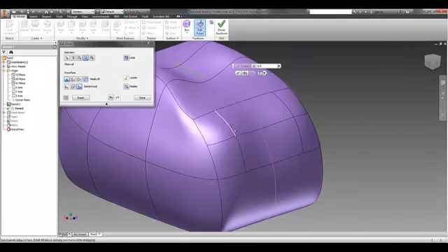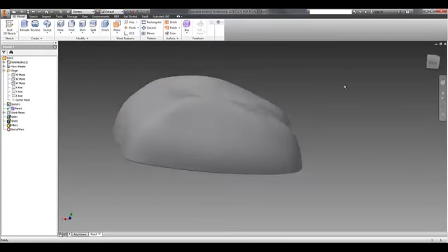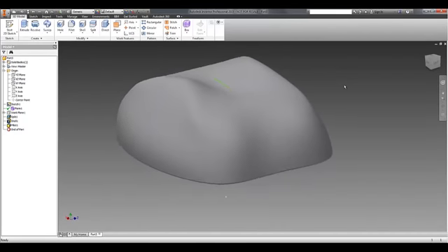Previously, without subdividing the face, I wouldn't have been able to pull the center of the face out. So you have to have a T-splines node or an edge to be able to manipulate that geometry. We'll finish the freeform again, and our downstream edits are still preserved.